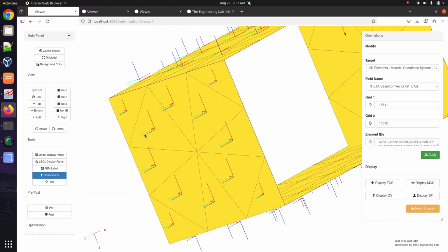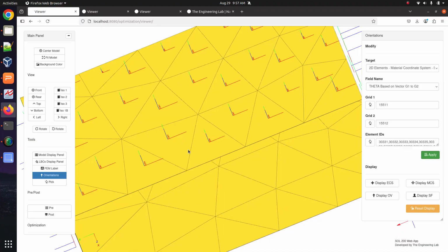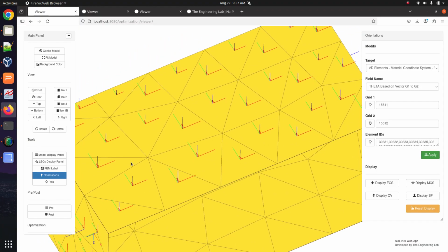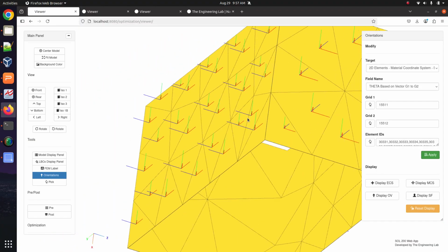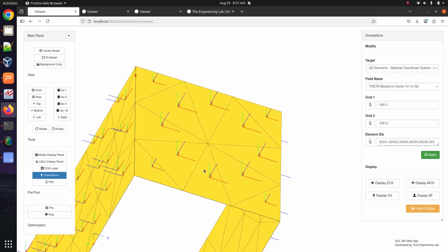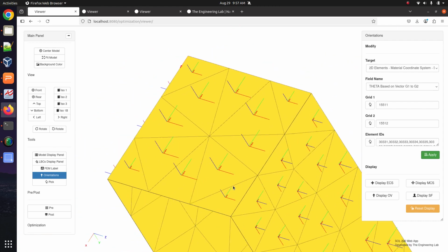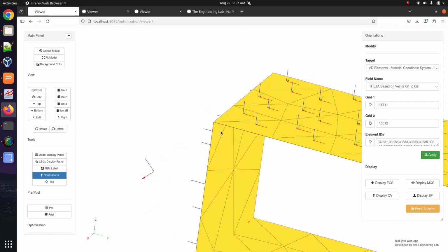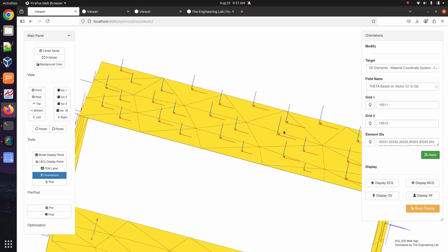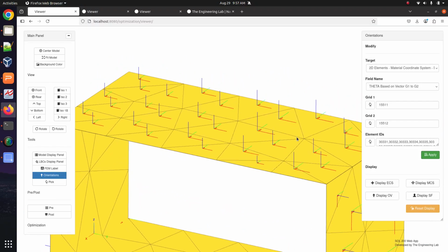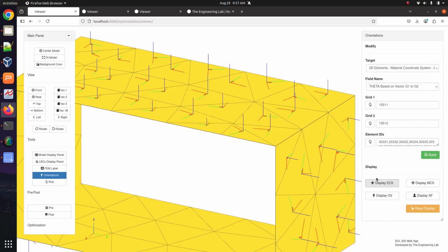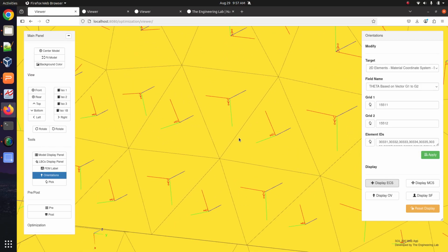So you can imagine if this was a laminate, we would drape our fiber along this direction. It would go around the corner along this direction. It would continue draping our fiber until we're going in this direction on the other side of the box. Whereas before, the finite element model had the 0 degree direction going in completely different directions.